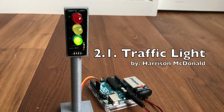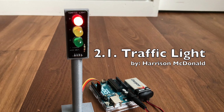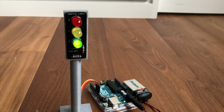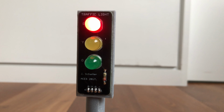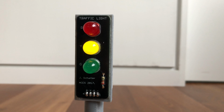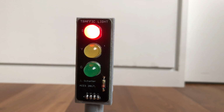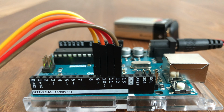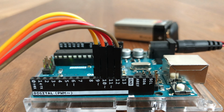This is the RSGC Project 2.1 traffic light, PCB designed by Jay Schaffer. The wiring gets right to the point, with only three 10mm red, yellow, and green LEDs and a single 220 ohm resistor. The traffic light connects to the Arduino Uno using 4 wires.